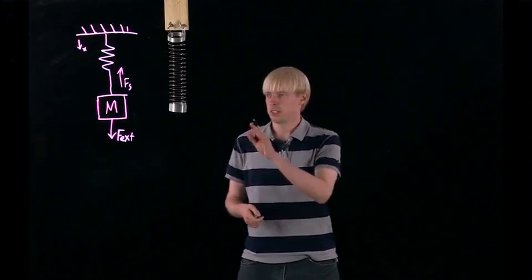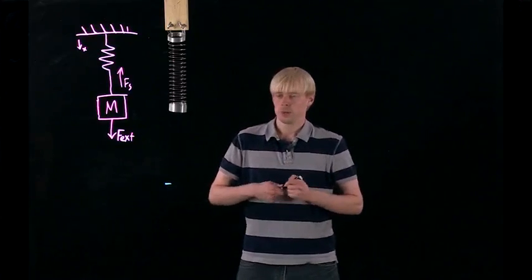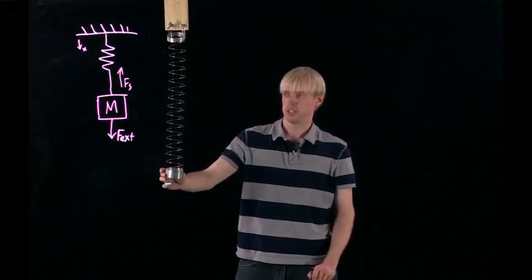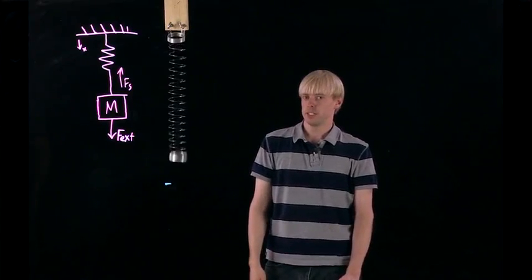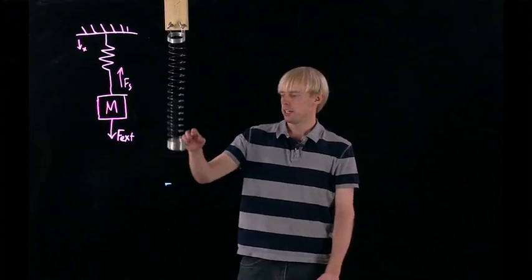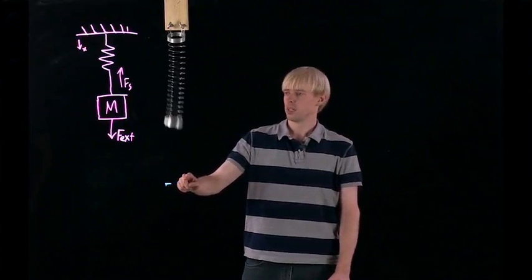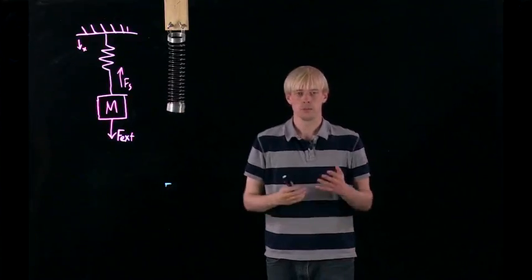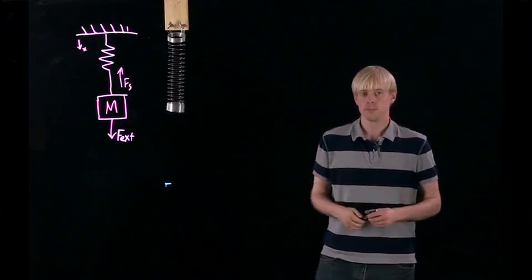To show you that, I'm just going to draw a line right down here, and we're going to take a look at what the spring does if I stretch it out at this point and just let it go. As you can see, the spring is pretty quickly losing a lot of its energy and not returning down to the point that we had drawn previously. That indicates some loss of energy, and that is due to damping in the system.